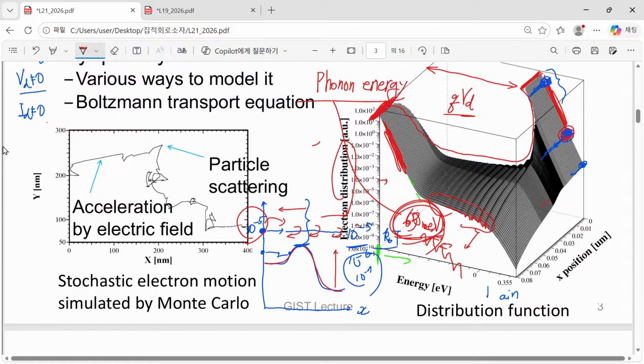So it simply means that once our electrons overcome this energy barrier, then at a certain position they can experience interaction with the 60 milli electron volt phonon. So it loses its energy by just 60 milli electron volt. Since its kinetic energy is so high, interacting with the phonon only once cannot release its entire kinetic energy.